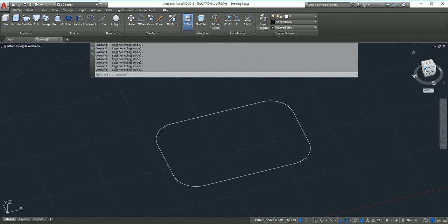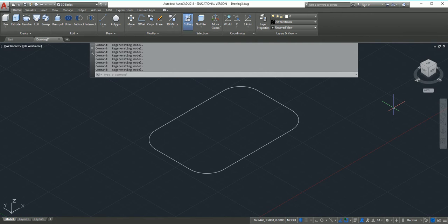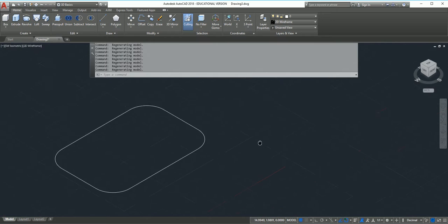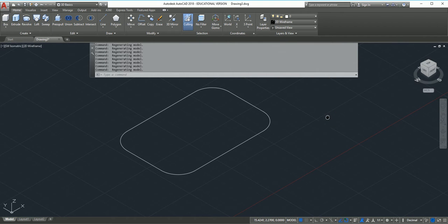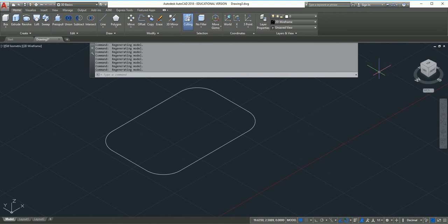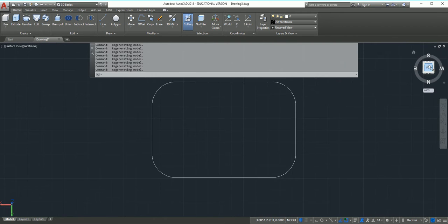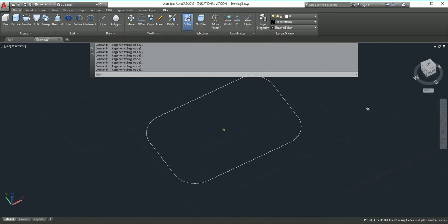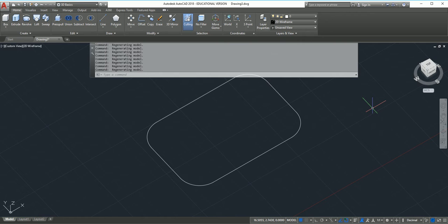Do you click the top, or where do you click? Click anywhere. It doesn't matter. Just like panning. When I click down on the wheel, I pan. No, I'm saying on the, what do you call it? The cube, the view. It's called the ViewCube. The ViewCube. Yeah. What'd you do? You just clicked on the top? It doesn't matter. You're automatically on top when you start drawing. Okay. To see it like that, is that what you want? Yeah. So hold shift and press down the wheel on your mouse like you're going to pan.